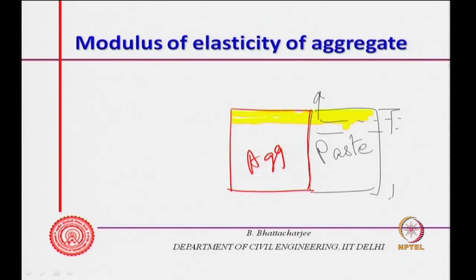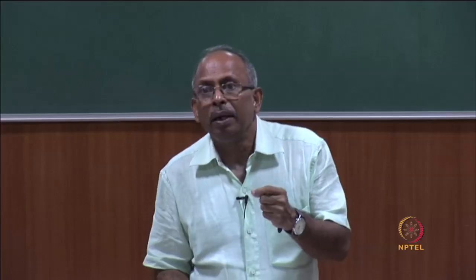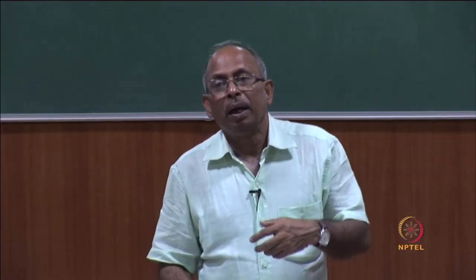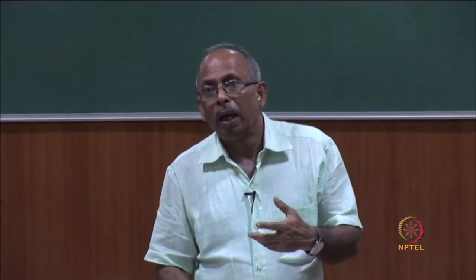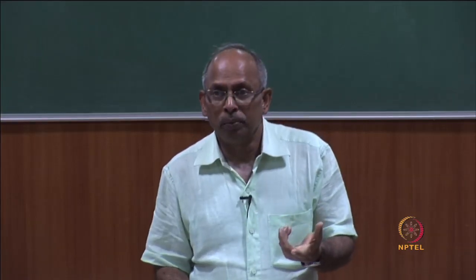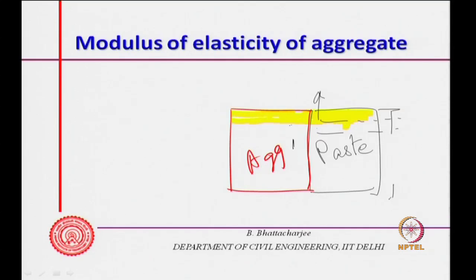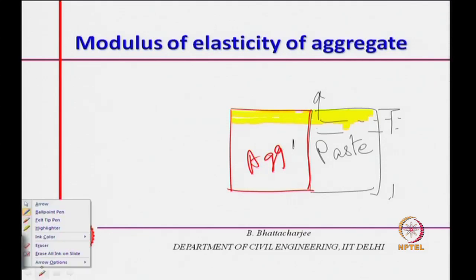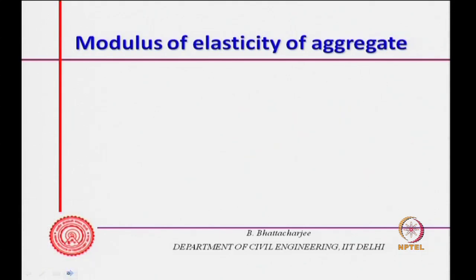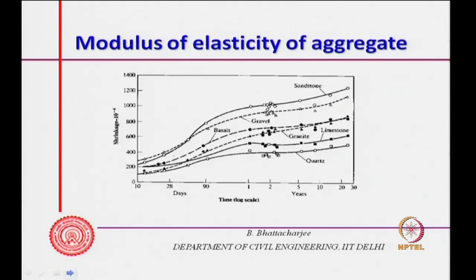For the same strain, the stress would be more if the modulus of elasticity is more. So, if this has a high modulus of elasticity, it will actually share more load for the same strain, and the paste will be less loaded, besides it will provide that restraint more. So, modulus of elasticity has a role. So, aggregate modulus of elasticity.